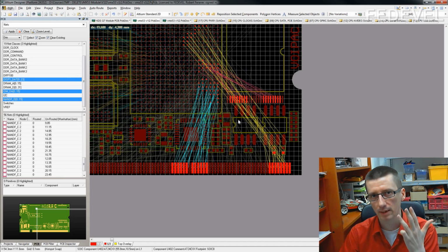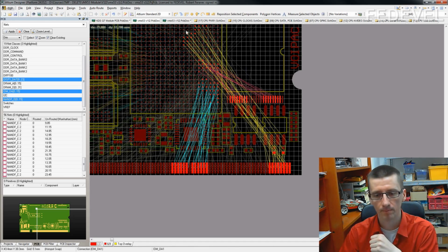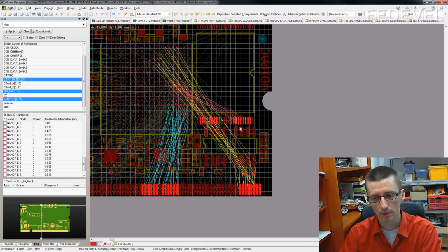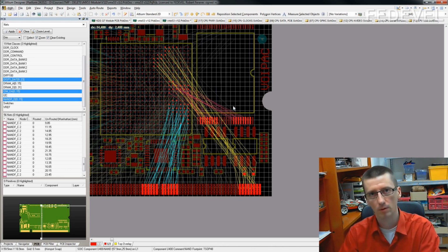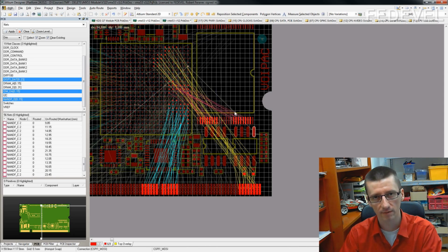clock, crystal, oscillator, and pull ups and pull downs. You don't have to connect them with the processor or something. Just do all the short tracks and place there all the vias, because once there are all the vias, you can see how much space you have for layout, and once you have done the layout, you don't have to do it again. If there are no vias and you do the layout, what may very easily happen is you place the via and you need to redraw the track. So place the vias first.